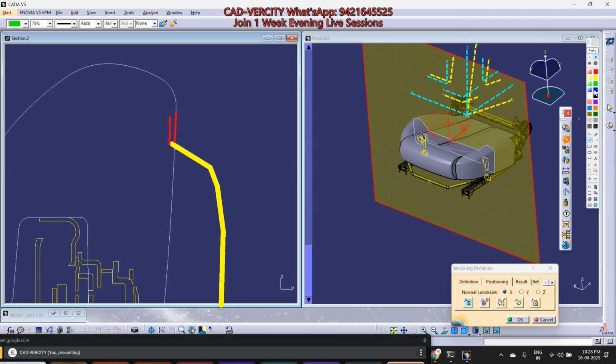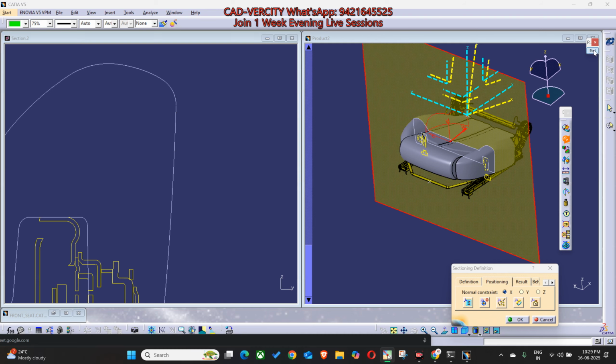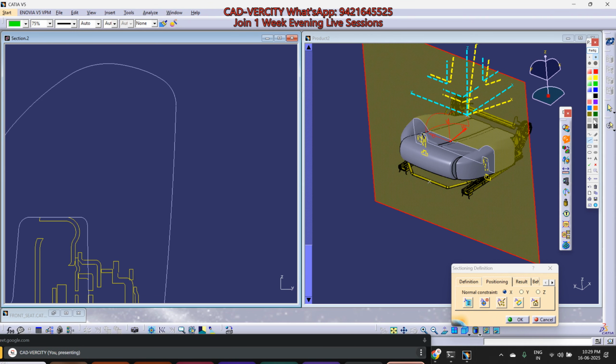See, this is a foam, to avoid gap. This is a foam. Let me again correct. This will be the side cover. And suppose this is your trim, with some offset value. This will be your leather or what we can say the fabric. We will keep this clash of 2 mm. Why? With the fabric.